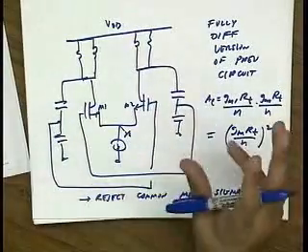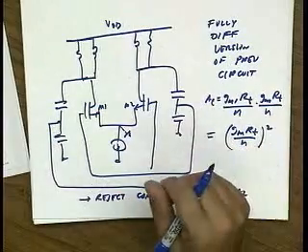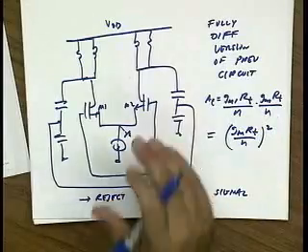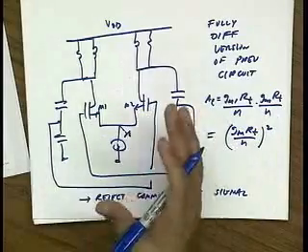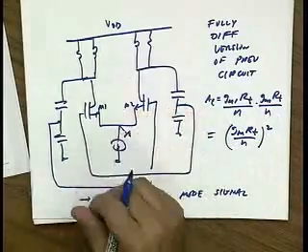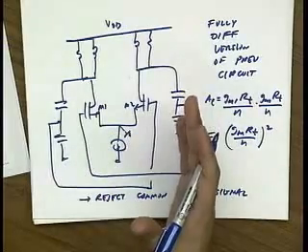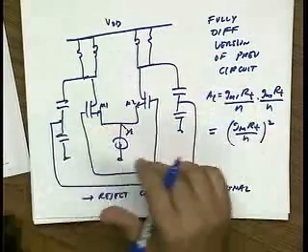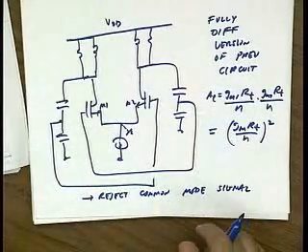So let's say this is a disturbance, an unwanted signal, that locks our VCO. That's a really bad thing. We're designing a VCO here to set up a reference for, let's say, our mixer. We want the frequency to be well defined. We don't want it to be influenced by other signals. And that's why going differential is so important.